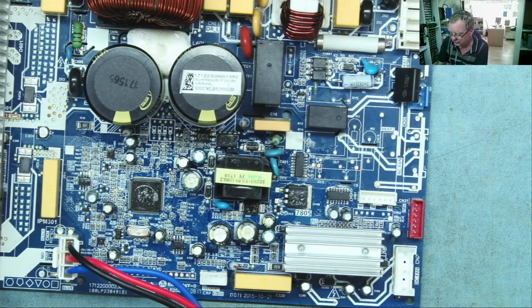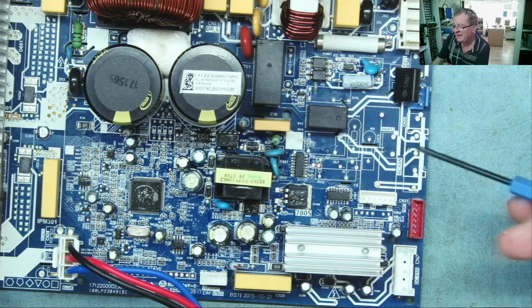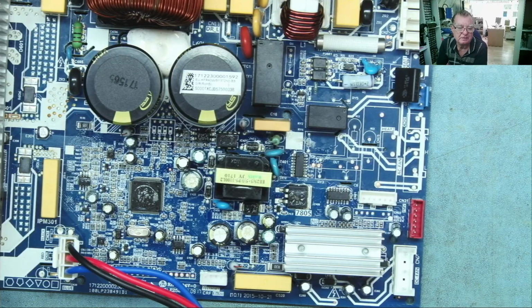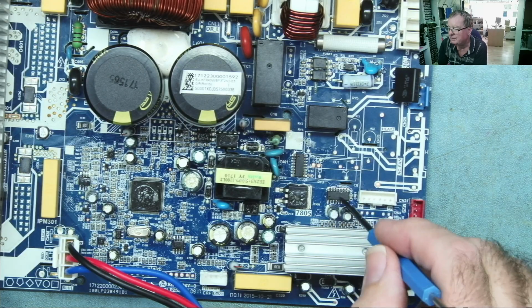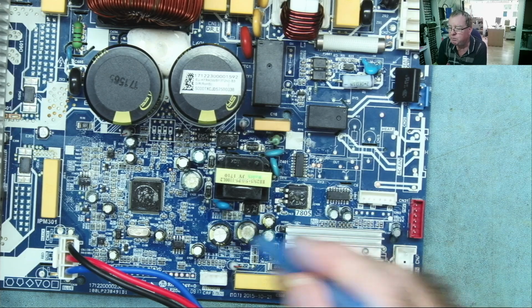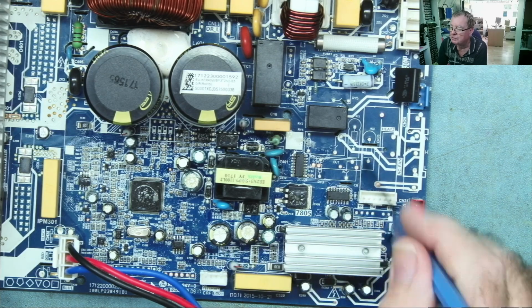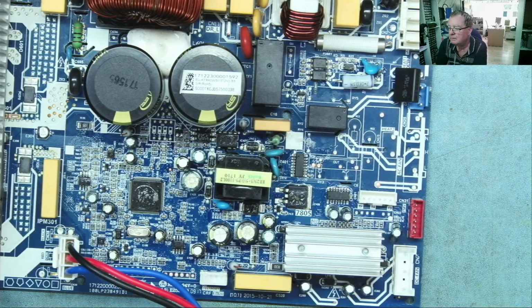One would be some problem with the device that's connected here. Another one is just voltage spikes. This is coming down maybe long cables, lightning nearby, anything like that causes some sort of surge or spike. That thing is the first in line, yeah? It'll probably save the processor because that will just take the surge and die, yeah?